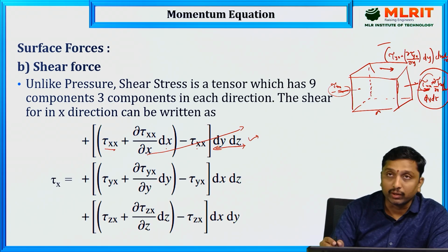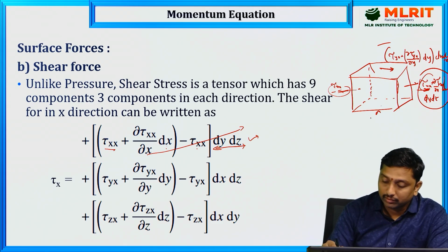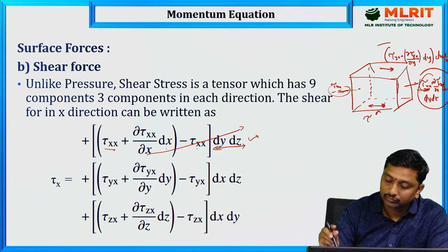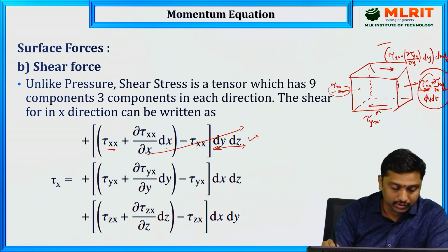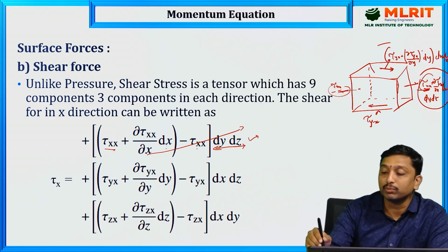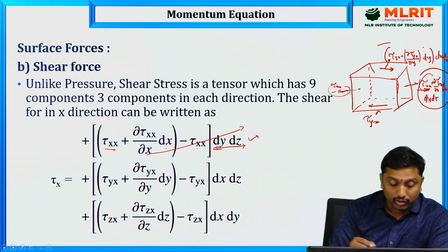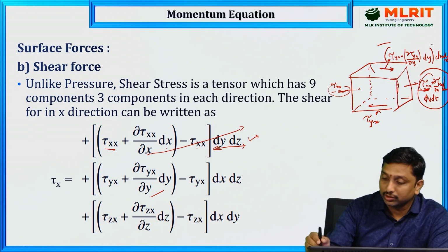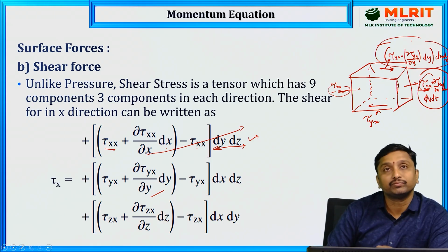Similarly, if you observe the bottom plane, this bottom plane will be having shear force as tau yx on the upper surface, as we have taken tau yx plus dou tau yx by dou y into dy, this is the plane.